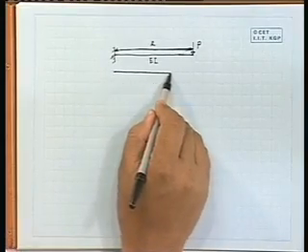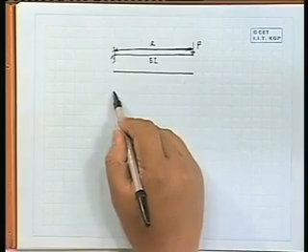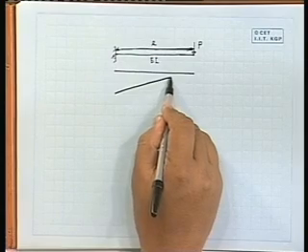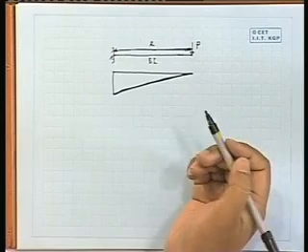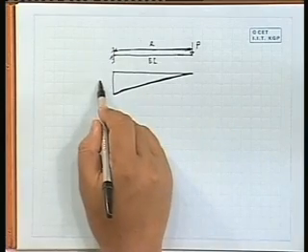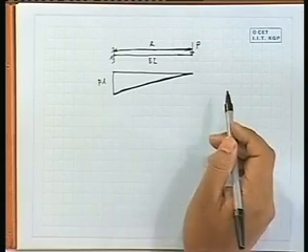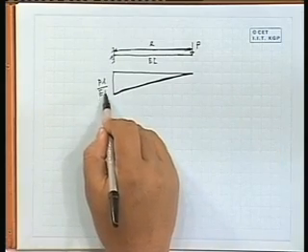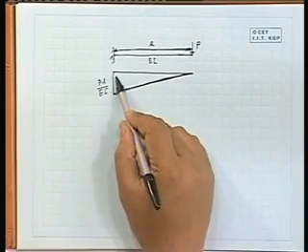So, our first job is we have to draw the bending moment diagram. It is a cantilever problem, we need not calculate the reactions because we have one free end, from that end we can start. So, P into x, that will be the expression of the bending moment diagram, or if we draw the bending moment diagram, it will be something like this. So, this value will be P into L. This is what your bending moment diagram, and if we divide it by EI, it will be M by EI diagram. Okay.